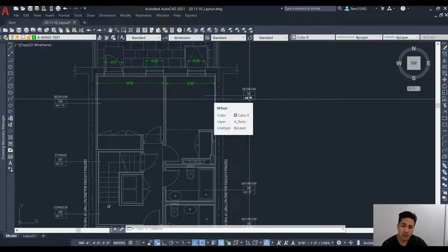So even though there is a building adjacent to the building, it's also possible there is some sort of air gap between it. So even though it is an adjacent building, we're going to assume that that wall is going to be an exterior wall because of that potential airspace that will be built between two adjacent buildings.